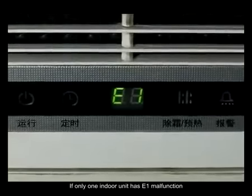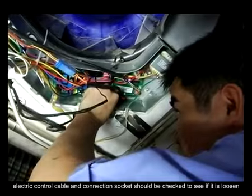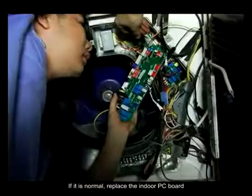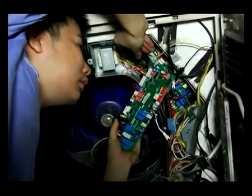If only one indoor unit has E1 malfunction, the electric control cable and connection socket should be checked to see if it is loosened. If it is normal, replace the indoor PC board.